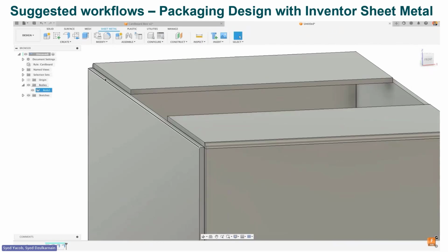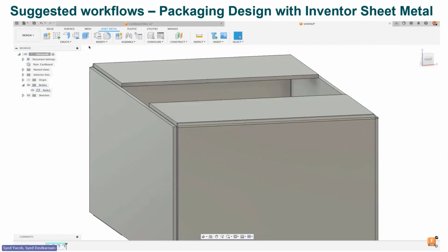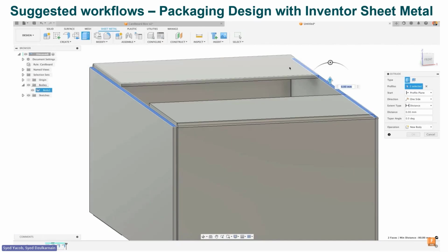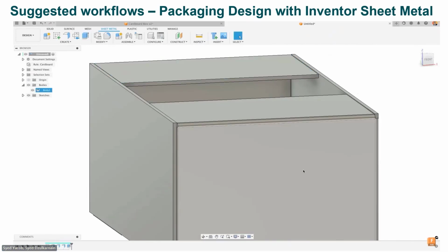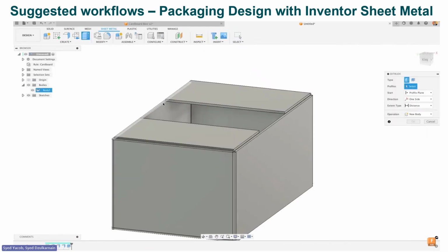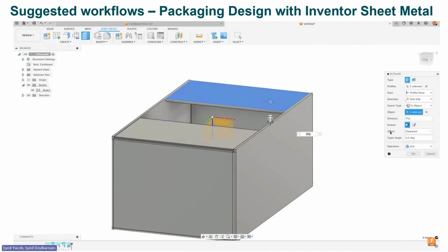And then maybe I want to make it go up a bit, not on the same level as that face, but instead going outside or inside, depending on how I want it to be. So let's say I select that, and then probably I extrude some face first, just to make sure that I added some extra height to it, to make sure it's aligned. I can just use that face to make sure that my extrusion is on the same height as that face. Otherwise I will have to manually measure and key in the values. Same thing that I just repeated at the bottom there, you get the same thing. So just extrude to the objects, and offset some clearance if I need to.